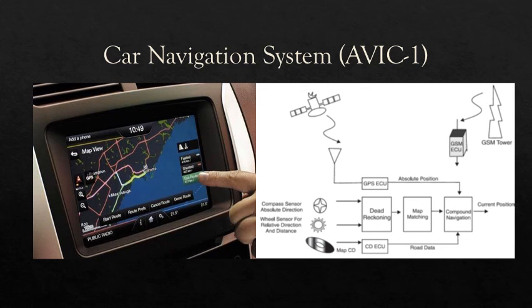Car navigation system. The navigation system indicates the location and running direction at the center of its CRT display. As the vehicle moves, one map after another is sent to the display automatically. The system is composed of a GPS receiver, earth magnetic sensor, speed sensor, horizontal antenna 13 cm in diameter and control unit, a CD-ROM driver unit and a 6-inch CRT.